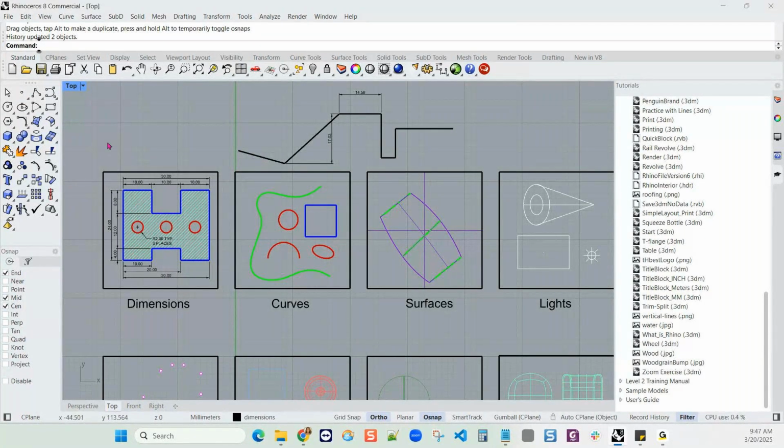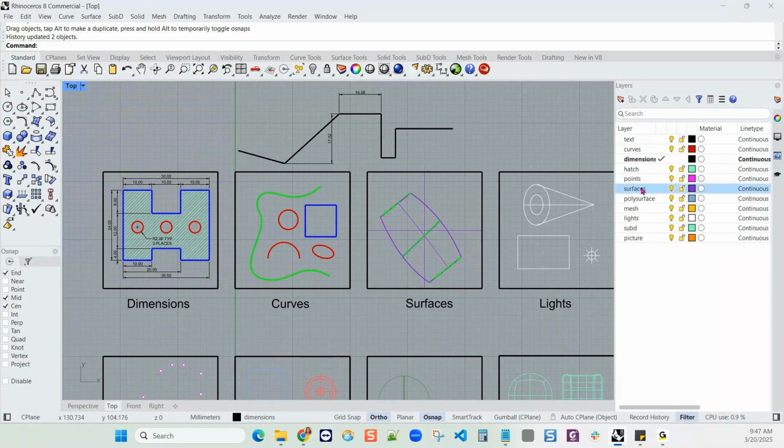In the early days of Rhino, I remember teaching a class, and the students in the class were like, well, we really just want to do 3D. It's like you can't separate the relationship between curves and getting to your 3D objects. If you create the curves correctly in the right place at the right size, then you'll have less editing to do with your surfaces downstream. So they are, again, really important.